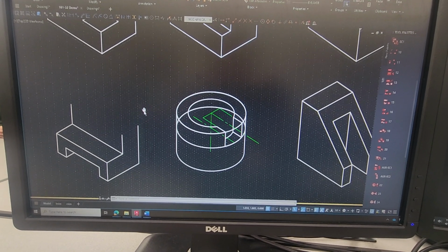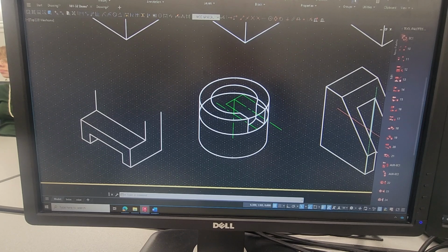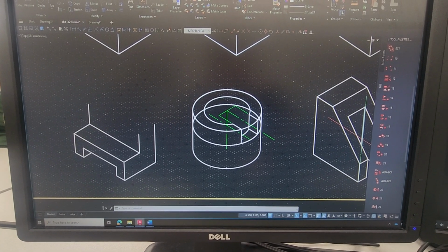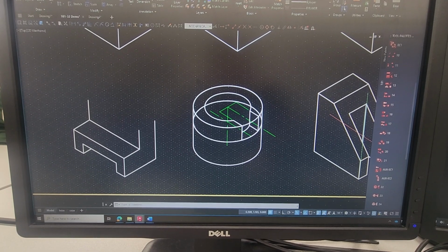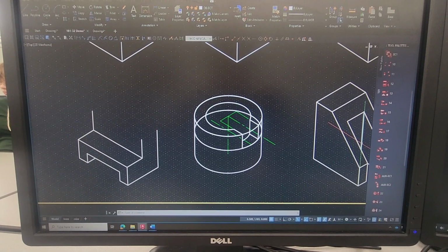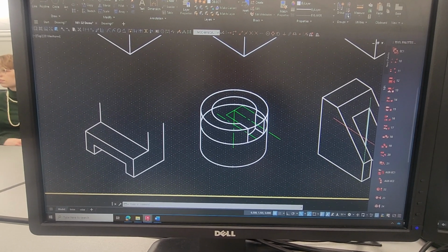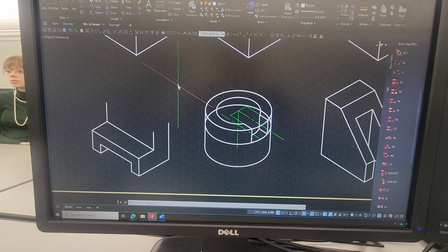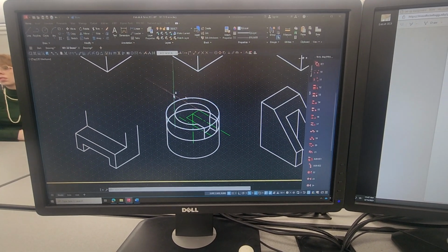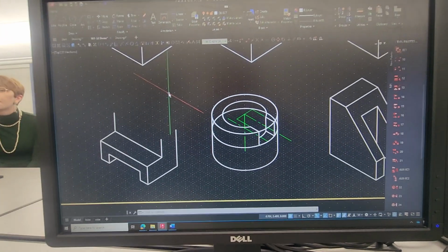Okay? All right, now the reason I say this is because we look at this particular object down here. Now we've got something that's round, and we recognize that as being a hole going through this thing, and that's absolutely fine. But it's not a circle, is it? And we learned back when we did our auxiliary drawings that we might have to make ellipses. Well, bear in mind, these are not actually ellipses. These are what we call isocircles, to go along with isometric drawings.